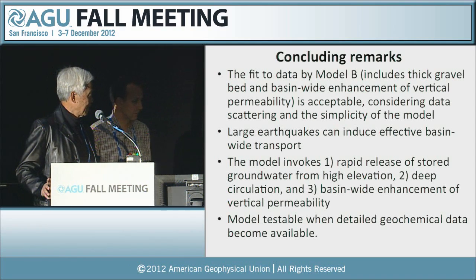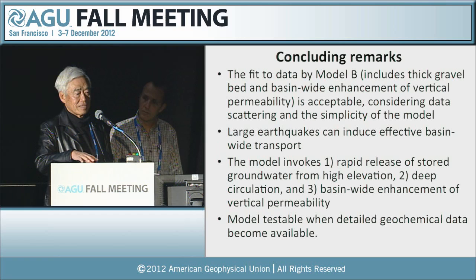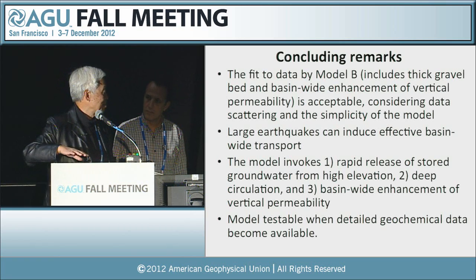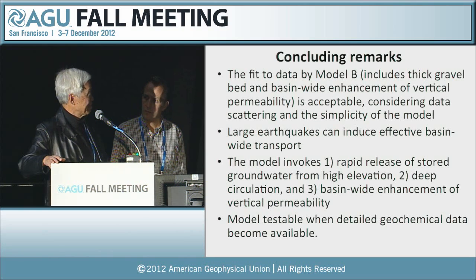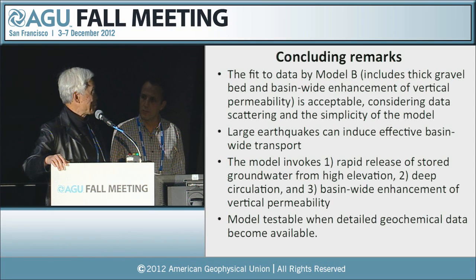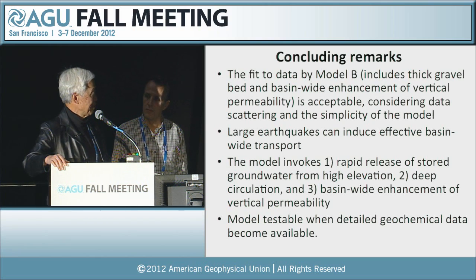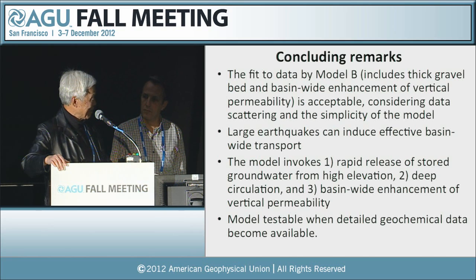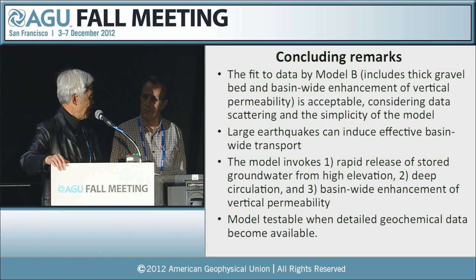I have a question. The subvertical cracks that you're talking about, is there field evidence for those subvertical cracks? Yes. Right after the earthquake, there was field mapping across the ruptured fault. And there is plenty of evidence showing the creation of subvertical cracks. And there's also evidence for increased vertical permeability by sudden downpour of water in tunnels. And there's also evidence from well water level that shows sudden drop in water level. And there's also evidence from temperature that shows water temperature has dropped, indicating downward flow, advection of water.